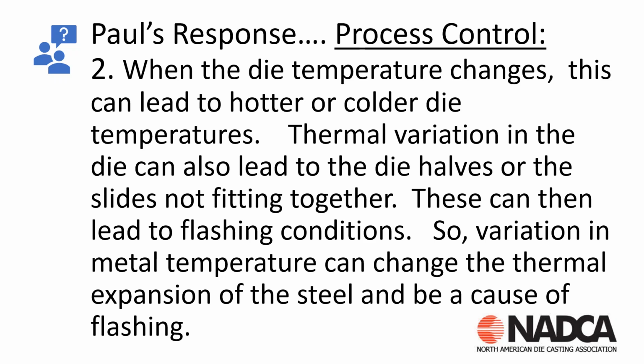So if your customer is asking you to hold something tighter, frankly, I would go back to the customer and say, why? What are we looking to do? If we have general tolerances of plus or minus 10 thousandths or anything critical we're machining, then frankly, holding a tighter temperature is just that, holding a tighter temperature. It's not going to affect the end product. So I think you should go back to your customer and ask, why are we doing this?